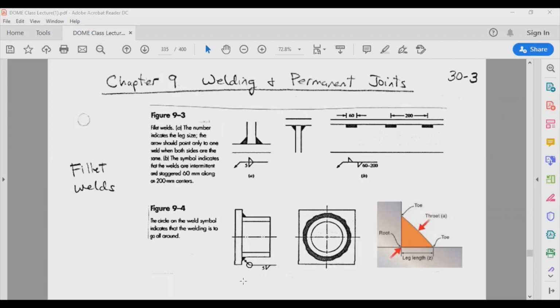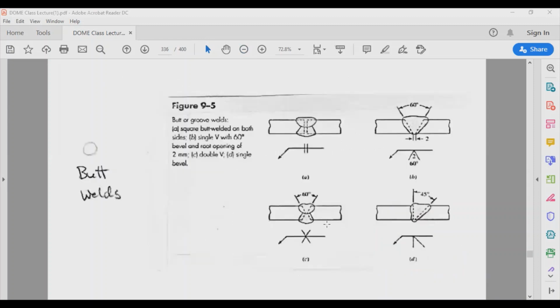In the case of a circular weld, basically what we're doing is you're going to specify this leg length of 5 millimeter, and then that 5 millimeter is going to be throughout along the flange, right? And then if you are looking at a top view over here, from this end, you are going to see that this weld is going to be looking like that. Okay, so it is pretty basic, like now, getting that throat and from the leg.